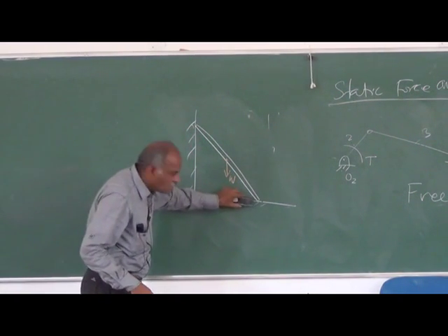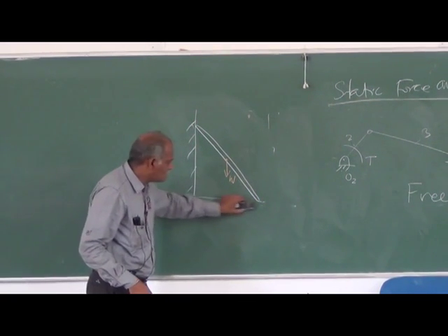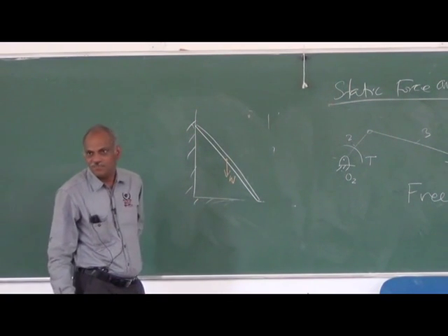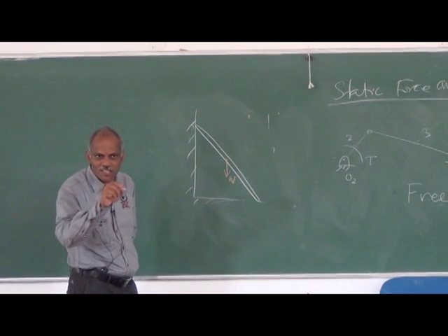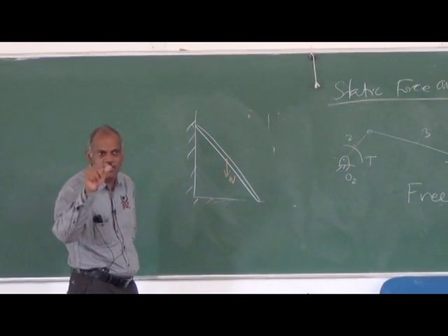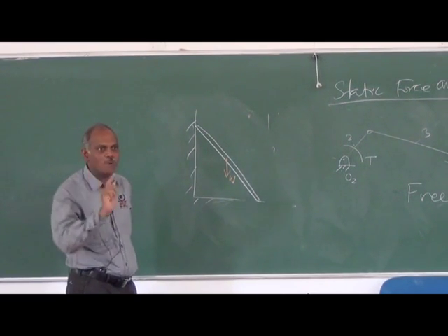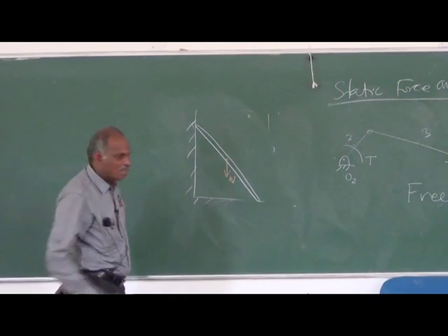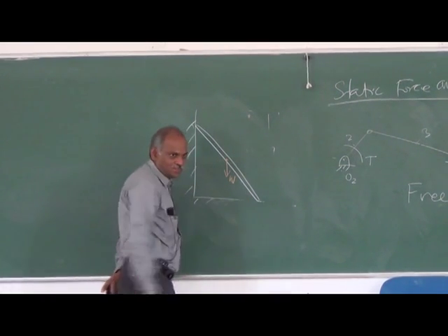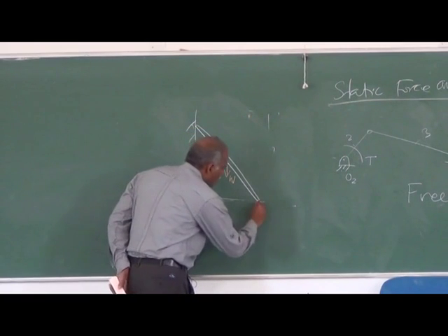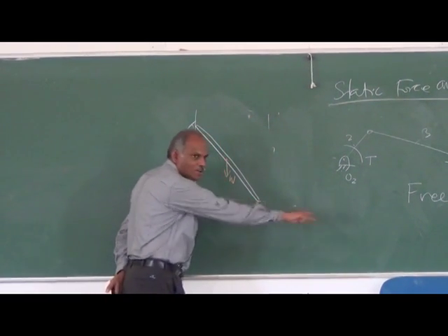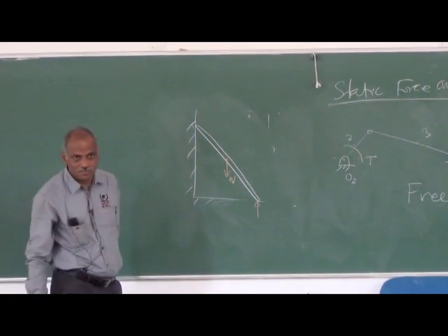The constraints are to be removed, not at free will. The constraints are to be replaced by appropriate reactions. There only the knowledge of appropriate reactions is needed. Suppose it is a frictionless floor, then the reaction will always be perpendicular to the surface.